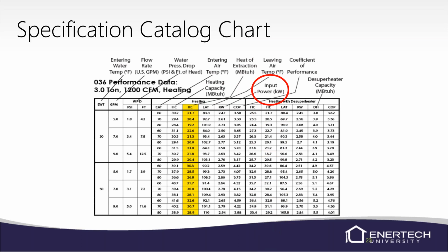That input, the kW, the power input, again, that's the compressor. Volts times amps equals watts. So that's what that number is. That's a kilowatt. Then you could actually take that 2.47 and multiply it times your 3.41, and then also multiply that by the efficiency of your compressor, and that'll give us our BTUs.